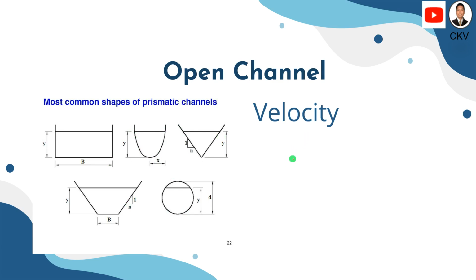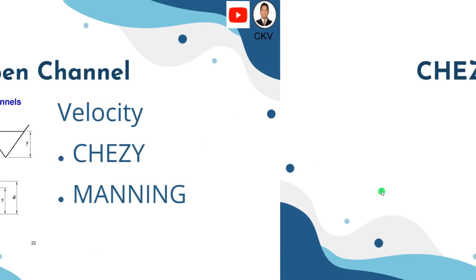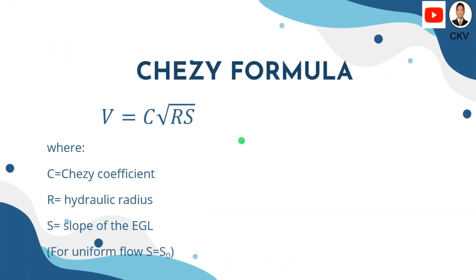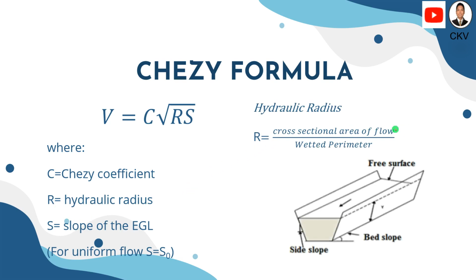In order for us to obtain the velocity in the open channel, we can compute that using the Chezy formula or the Manning formula. For the Chezy formula, here's the equivalent solution for the velocity. It is equal to C, or the Chezy coefficient, multiplied by the square root of RS. R is the hydraulic radius and S is the slope of the energy grade line. Hydraulic radius can be computed by dividing the cross-sectional area of flow by the wetted perimeter.